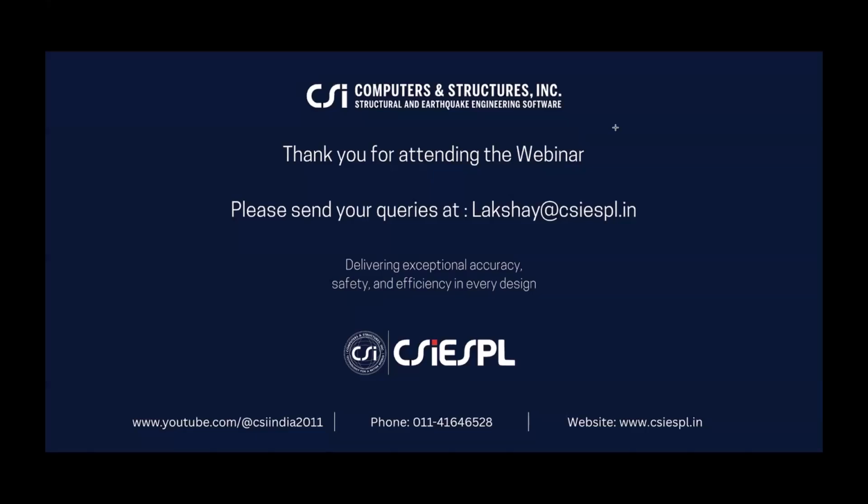That is the usual way we do it. Finally, once we converted into lateral forces, user-defined forces, I removed those two load cases for simplicity. I think it is better to keep it that way, or else there will be confusion from multiple cases. The program is also capable of handling it when you switch off certain cases. The load combinations for those will not have the data, and it will give a warning and continue to perform the design for the available load combinations. So you can continue, but it is better that you simplify your load combinations, which I have done in the presentation model.